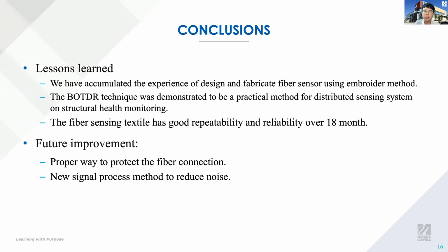After these two field tests of sensing textile, we have accumulated experience in designing and fabricating fiber sensors using the embroidery method. The BOTDR technique was demonstrated to be a practical method for distributed sensing systems in structural health monitoring. The fiber sensing system has good repeatability and reliability over 18 months. In the future, we will try to find a proper way to protect the fiber connection under the bridge, and also develop new signal processing methods to reduce noise.